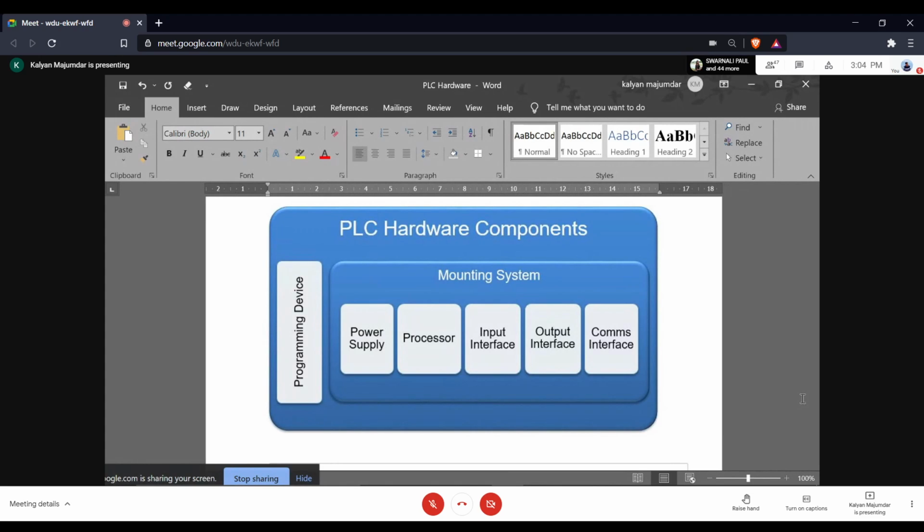That is basically a computer which collects information from all the PLCs, from the entire process, all machines in this particular factory, all equipments in the factory. All the data is brought to a centralized computer, and there you have that visualization, more commonly referred to as HMI. You did one page, they'll have many pages of such visualizations, which give you information regarding the entire machine, entire plant, entire process. So obviously, since you need data from multiple PLCs, you need to connect all of them in a network. And again, for that, you require a communication interface. Again, typically that's an Ethernet interface. So a PLC requires a communication interface for multiple reasons, and that is why a PLC by default has communication interfaces. And the last thing is this mounting system. I'll come to this a little later.